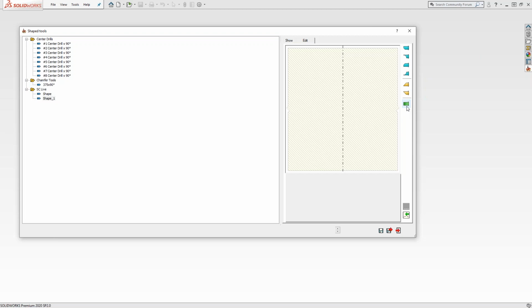This works really good if your tooling vendor has sent you a solid model of your tool itself. What you can do is just open up that solid model and go into the sketch, and then you can actually copy that sketch over and bring it in. So when Mark clicks on import, he can hit paste and bring that sketch in there, and then you can just use that as your sketch geometry, or you can actually insert that tool right into that import sketch button as well. And like I said, SolidCAM is just looking for that revolve and then just chain half of that tool.